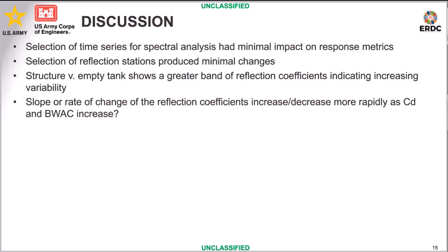I think I forgot to mention how the energy transmitted versus energy incident is computed. It's computed with those virtual gauges with a certain spacing that generates a high temporal resolution time series, which we then do spectral analysis on through FFT, and sum that total energy from the power spectral density function.